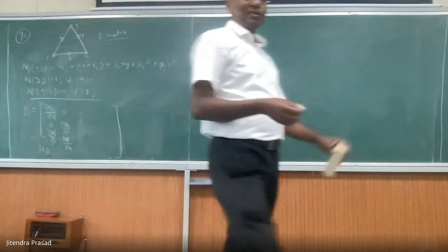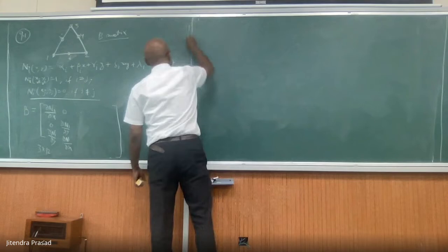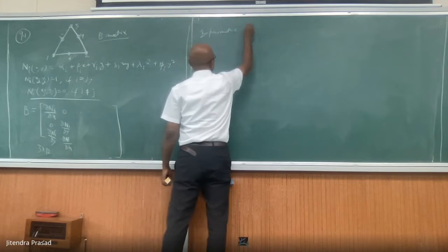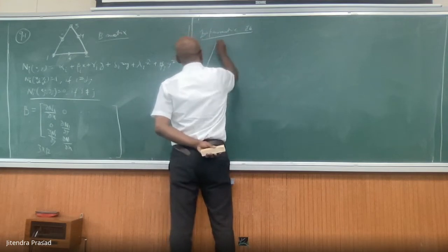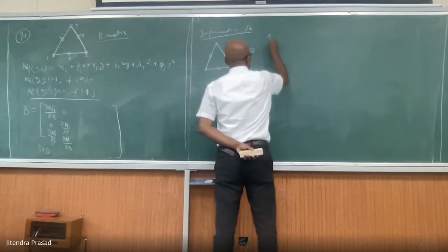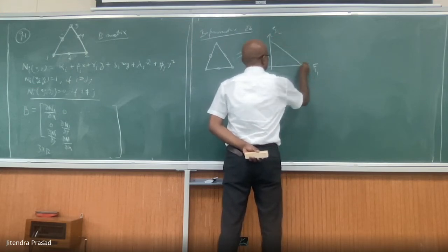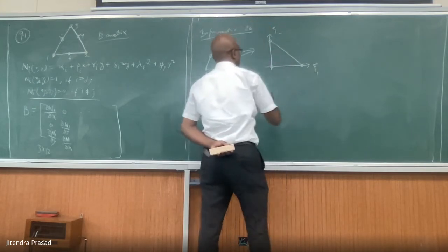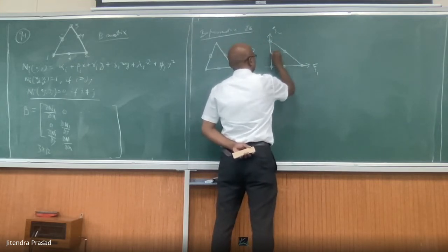So once you have that, you construct it. This is one way of doing it. You can also use this as an isoparametric element. The other way, you convert this to the Xi1, Xi2 system, and you have exactly like this.